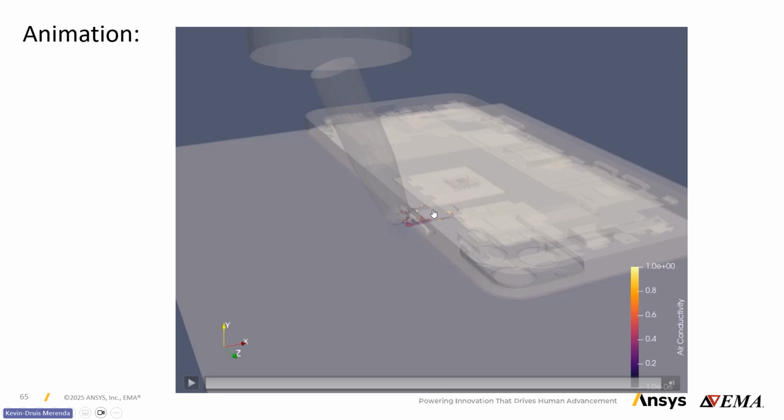One thing to note is we did ramp up the potential of the gun to be able to get this much arcing. At 15 kV, we wouldn't have the same behavior as we did here at 24 or 25 kV. So depending on the standard and depending on your analysis, you're going to have different behaviors, and all of these can be accounted for in the tool and tell you where the consequences are.